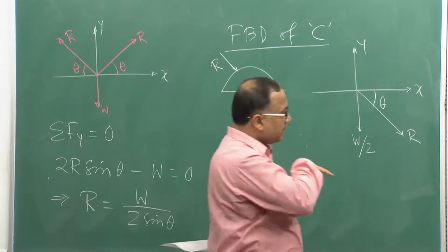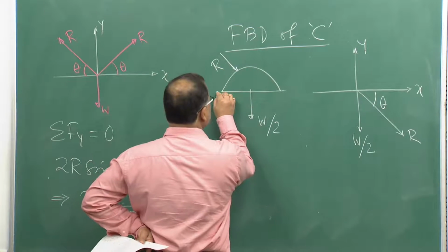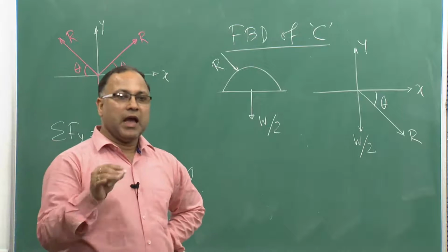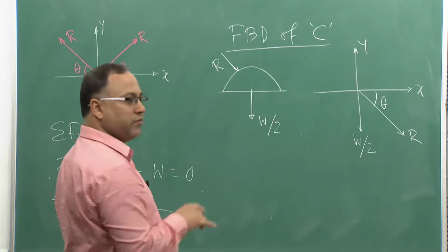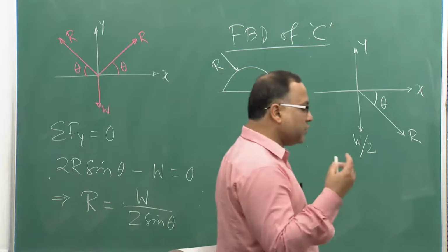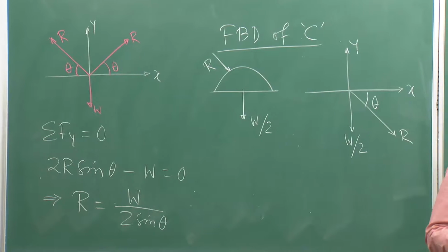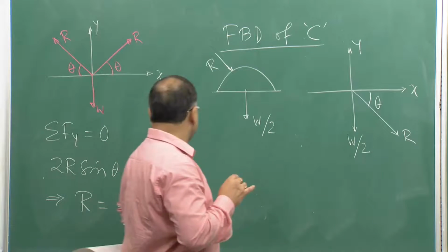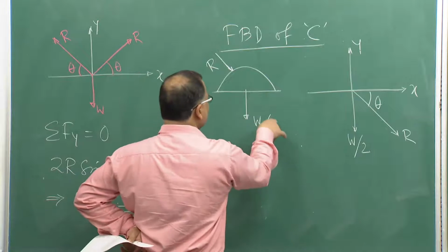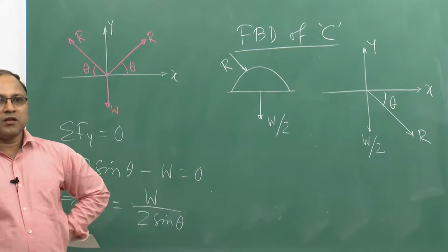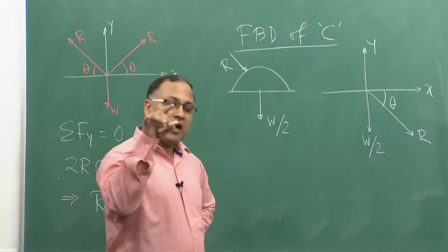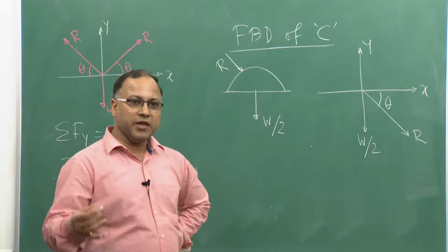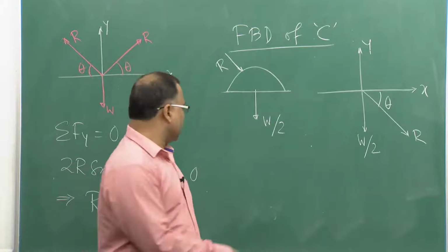Therefore, this is the interface between the half cylinder and the tabletop as shown in the figure. So, if you want to know how much friction force is getting developed, then you need to know the magnitude of N, capital N, the normal force. At the tabletop this W by 2 is anyway acting, that is the weight of the half cylinder C. Now, due to this R, some contribution will be coming towards the normal force N. So, that we are going to find out.